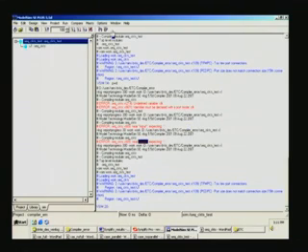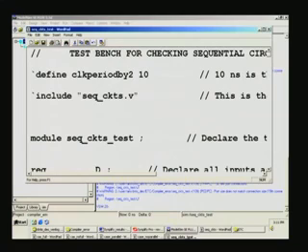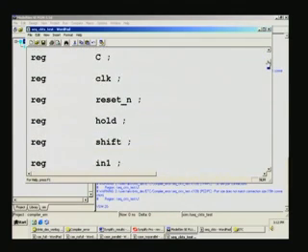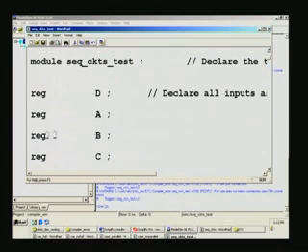And all along we have been looking into the design file. So, let us have a look at the test bench. We will create one or two errors there also and get a feel of it. And test bench is here, and so we will not repeat what we have already seen, for example, define, etc., and module. So, what we will do is, I was pointing out that inputs or outputs are differently declared. Here it is reg instead of wire normally. So let us declare this as wire and find out.